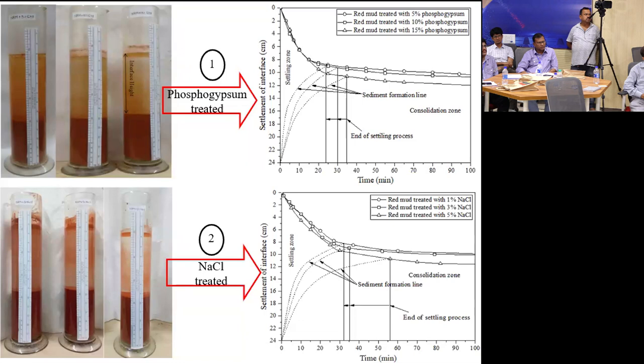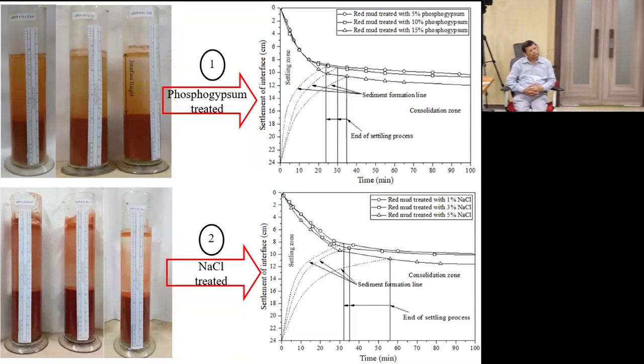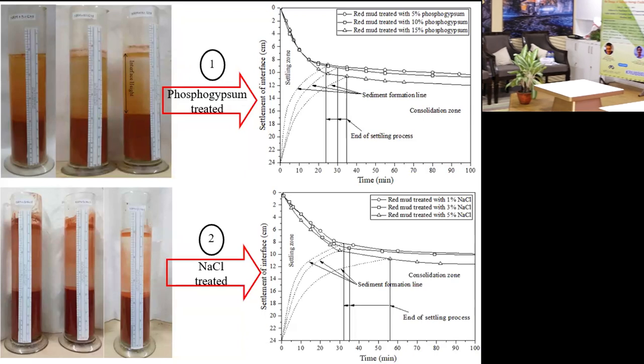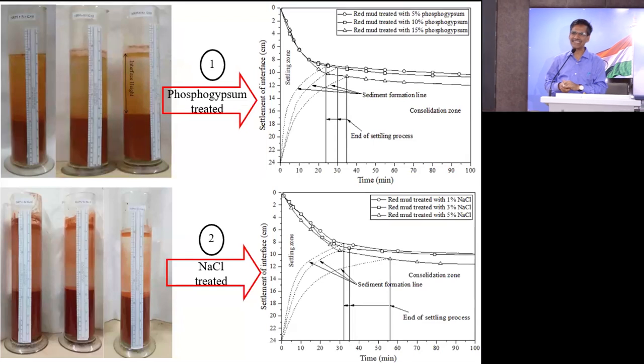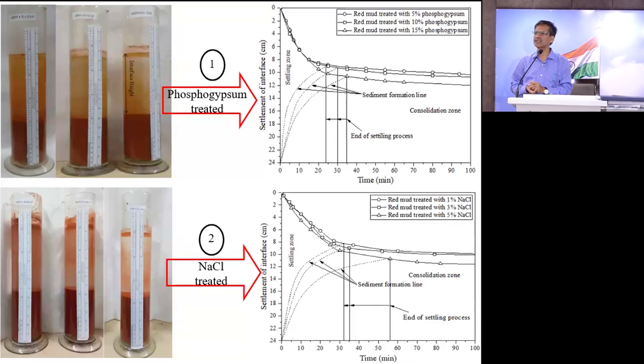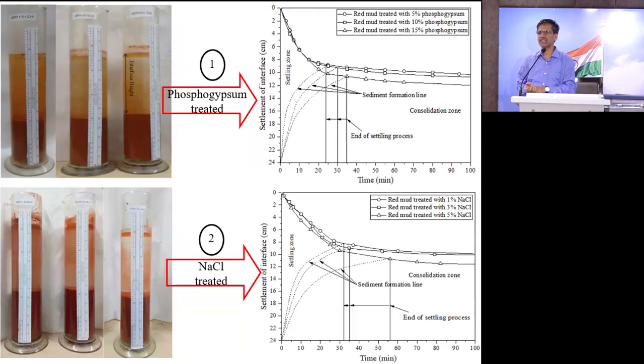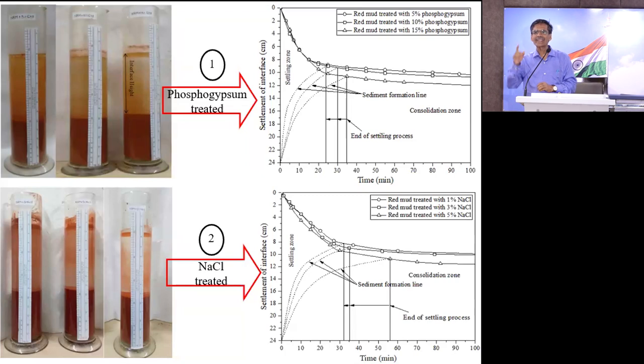Then another problem was the fly ash lime gypsum brick. It was breakable, it would break immediately. So I had to do it in the laboratory, I added 8 to 9%, and they told the contractor you have to build it here and manufacture it yourself. So every day you are manufacturing 8,000 to 24,000 bricks. Then in all that 450 crore project, they only used fly ash brick. So once upon a time, fly ash was also considered hazardous. They were not allowed to dump it in the open ground. Only after 2016 are they now saying you can dump it, mine filling, putting it everywhere. But that was not there before.